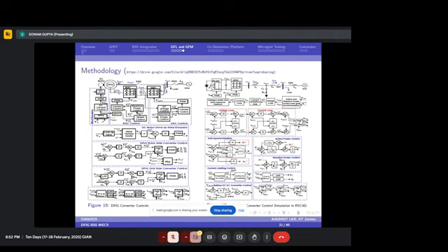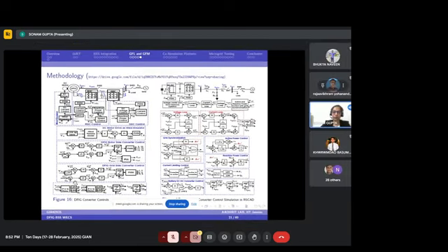For the grid side converter, it maintains the DC link voltage, and it continuously works on the unity power factor by ensuring zero reactive power management on the grid side. Here we can see the main change in the grid forming battery storage systems, because we are upgrading the control of the battery storage system from grid following to grid forming.